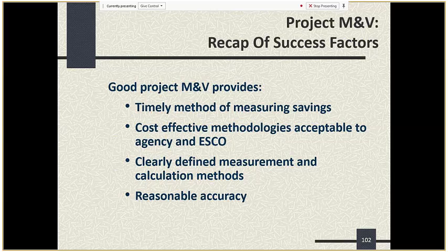And it was also true that a lot of the air handler VFDs were inoperable or in hand or bypass mode as well, right? Correct, just really from age and deferred maintenance. Yeah, so most of the AHUs were operating at full speed most of the time. Or bypass, yes.